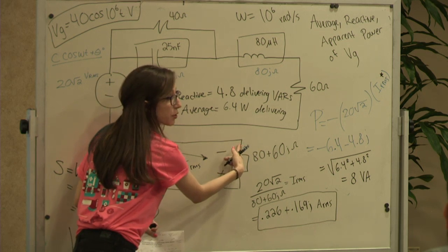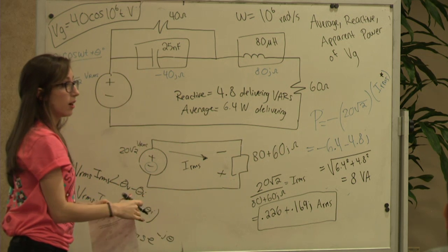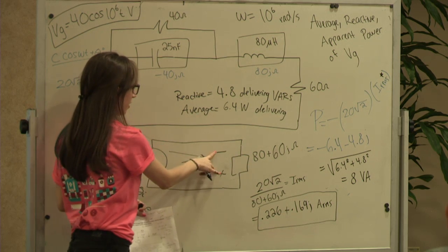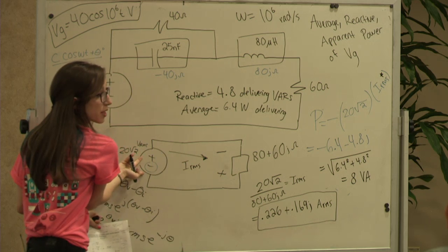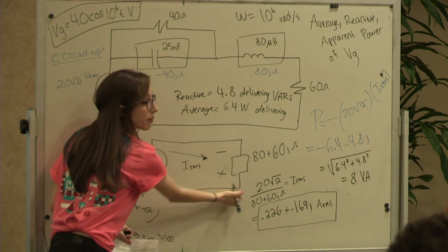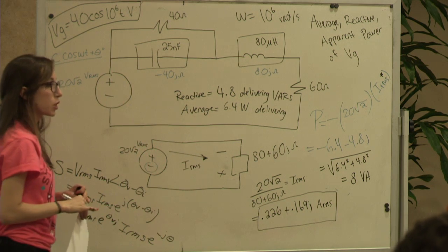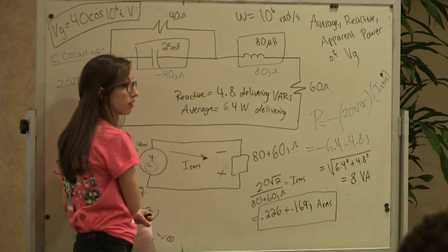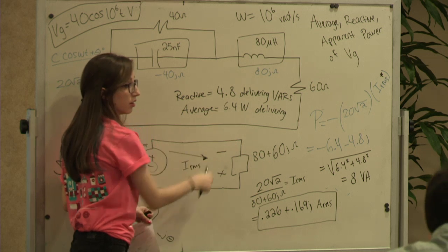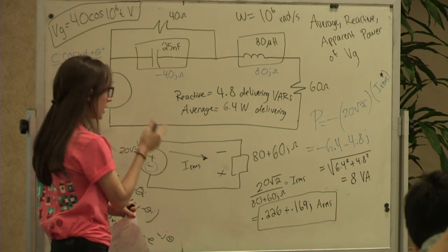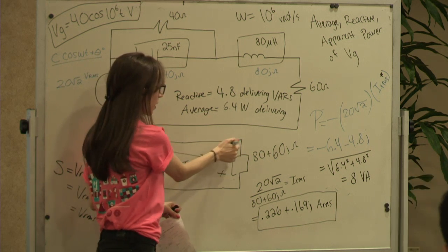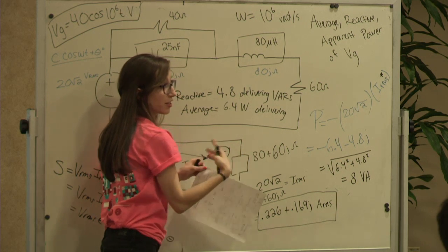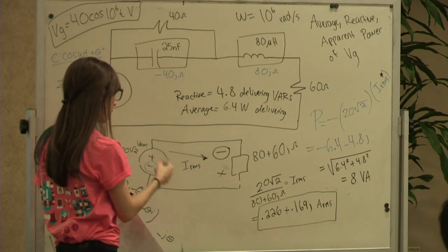The voltage across here would be negative 20 root 2. If you flip the signs, because they're in parallel, they're supposed to have the same voltage, and it can't have it unless they're showing the same polarity. Plus, plus, minus, minus. So you can assign it like that, but you have to remember to put a negative out front when you're doing your Ohm's law, because now it's actually going to be a double negative. Your IRMS that you're trying to solve for is going in the negative, and likewise the voltage over this is a negative, so it'll cancel out and become a positive, which is I think what we got, right?